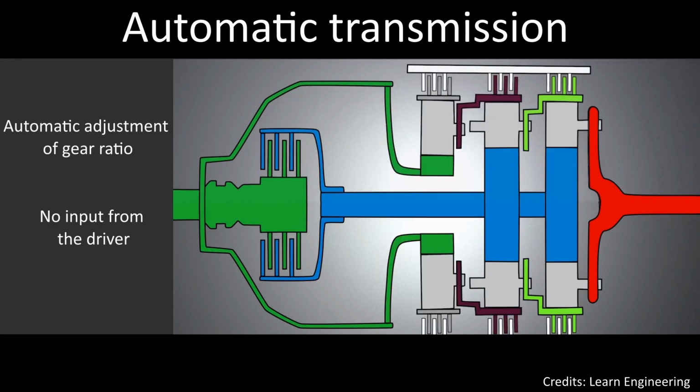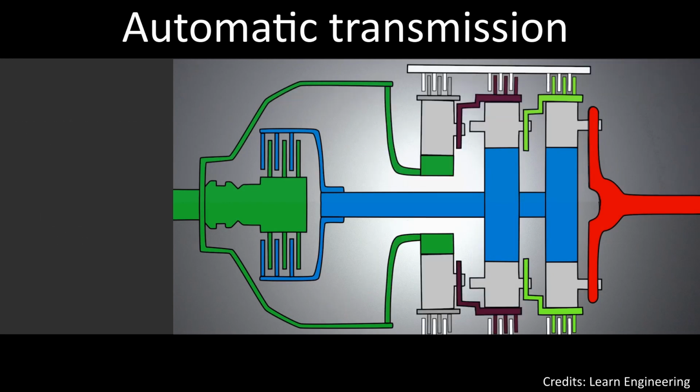Maybe you are wondering, why should I prefer an automatic transmission to a manual one? The advantage of an automatic transmission is the lack of a clutch pedal and a manual gear stick. This allows the driver to not focus on these two steps, increasing the attention on the road. Moreover, an automatic transmission increases the life of the system because it changes the gear perfectly, without any human errors that could wear the gear and the clutch. Changing the gear perfectly, it also improves the overall performance and efficiency of the vehicle.